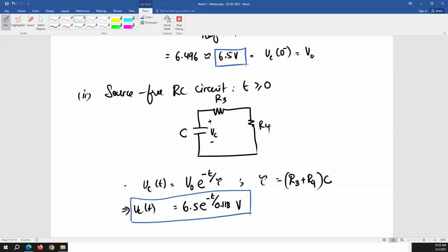then the capacitor is going to hold its charge. When the waveform is going down, it's going to start discharging, but it's going to take its time. And by the time the next waveform arrives, it's going to start charging the capacitor again. So your capacitor voltage is going to be pretty much standstill, because the output, let's say, of the full bridge rectifier is like this.